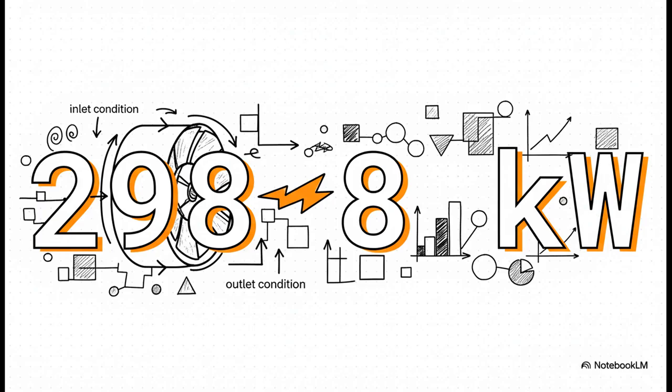And to make this completely real, the source material actually runs the numbers for a steam turbine. By plugging the conditions at the inlet and the outlet into our steady flow energy equation, the power output is calculated to be 298.8 kilowatts. So this isn't just theory, right? It's a practical tool that gives us hard, tangible numbers that we can use to build things.